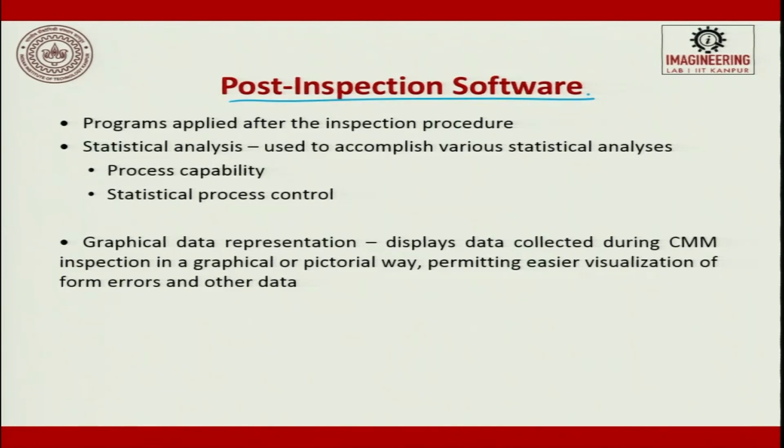Post inspection software. So, these are the programs applied after the inspection. You have done the measurement, now you have to get the deviation chart. So, that is called programs applied after the inspection procedure. We look at statistical analysis, like process capability and statistical process control. This can be done, or it can be graphical data representation, that is what I said, deviation. It displays the data collected during CMM inspection in a graphical or pictorial way, permitting easier visualization of the form errors and the other data. So, post inspection software does statistical analysis and graphical data representation.